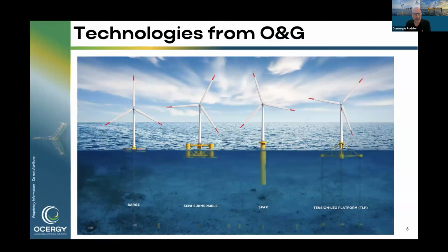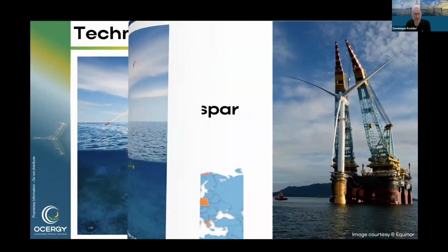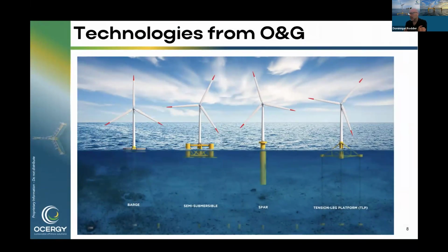When you're in oil and gas and you have a riser, you want a dry tree, meaning that the head of your well is at the platform, so you have control access of your well. You don't want to move vertically, because your riser is a steel pipe, right? You have to have a platform that has no heave. So those are the spars and the TLPs.